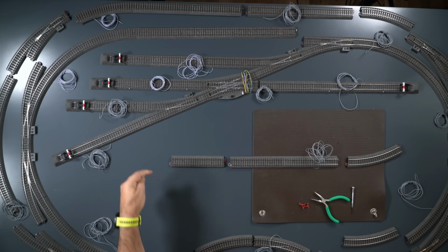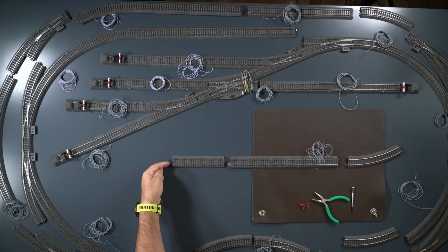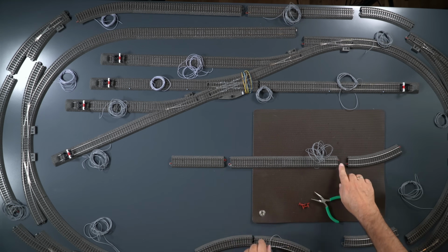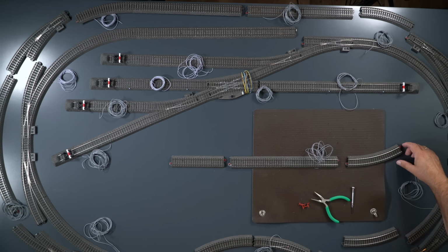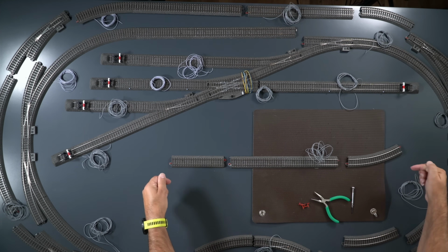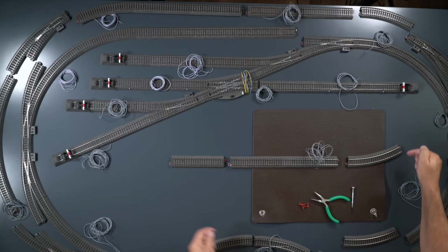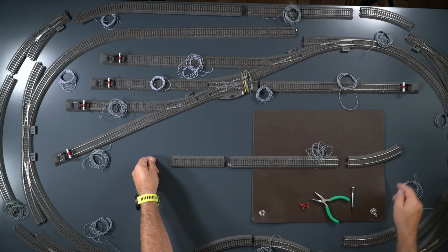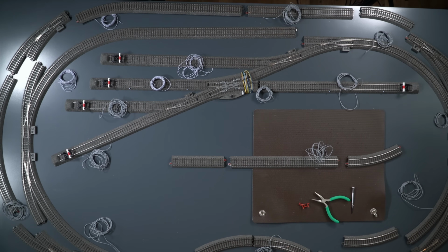Now, of course, I have isolated the center conductor here, then also isolated the transitions from each other again. Here once more isolated the center conductor, and the same here, and finally on the other side as well. But that's not enough yet, because the track continues here with another rail, and as we've learned, the 2 tabs are connected to each other. That means on the counterpart of the track and also here where the track will later be connected, the center conductor also needs to be isolated again in that direction.